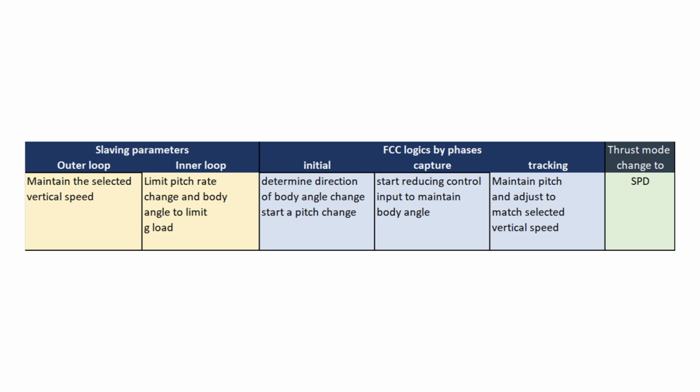The capture phase is to reduce the change in body angle in order to maintain constant pitch, and in the tracking, of course, the pitch remains basically constant and small adjustments are made in order to maintain the selected vertical speed.